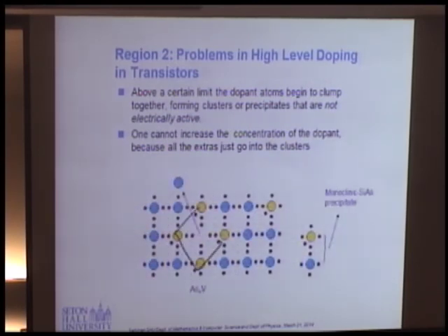This happens. You get arsenic 4 vacancy clusters kicking out the silicon, and you get a vacancy and arsenic 4 vacancy. Why do you get this state? Because it's energetically more favorable. But that's not a good state. You don't have any free electrons for that. It just kills your conductive behavior. There's no carriers. So that's not wanted. We don't want this.